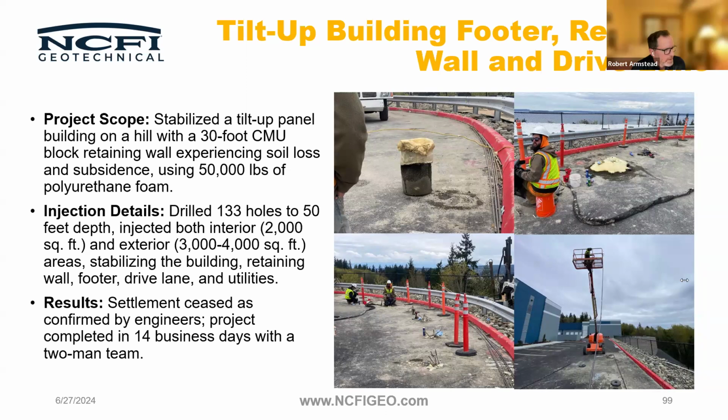If the contractor accidentally excavates too much below the footing, can they backfill it with polyurethane, then cut it back to grade after it's swelled, assuming column footing, asking to see if the foam itself is strong enough to support the footing? Well, the foam is going to be stronger than the dirt in most cases, but it's not the easiest thing to cut into with a piece of equipment. It's got great tensile strength and great shear strength.